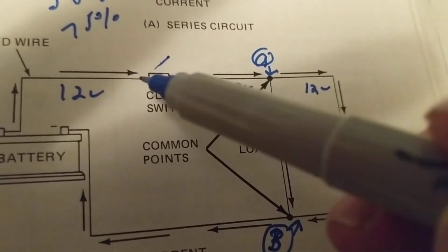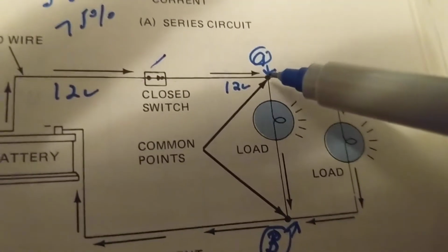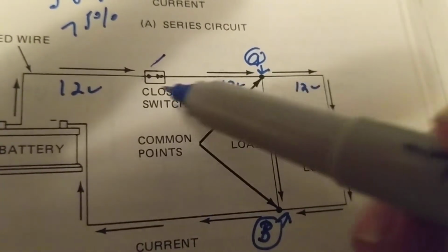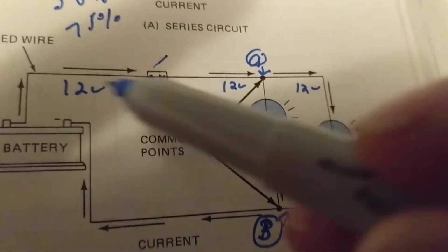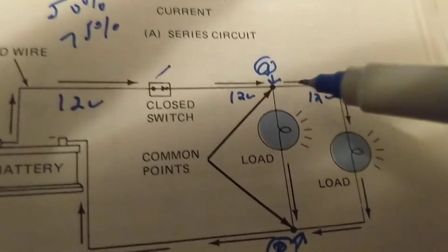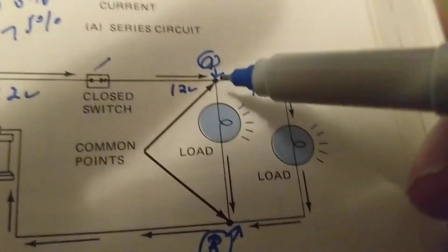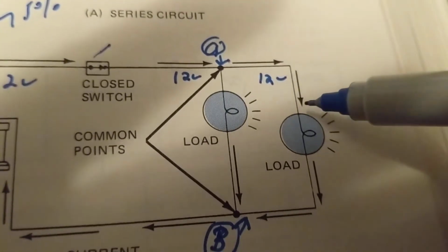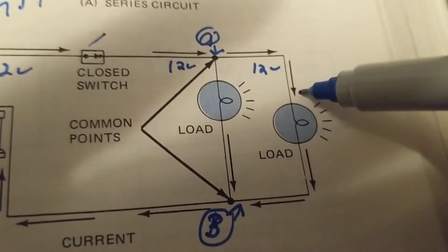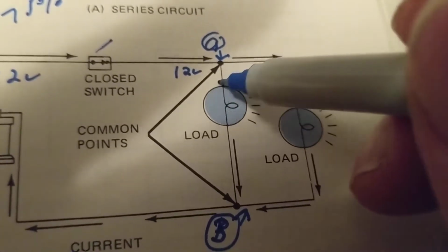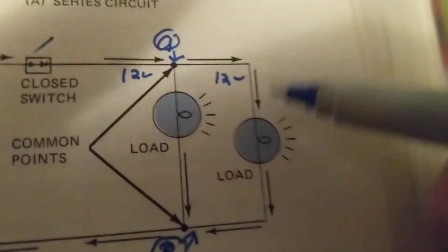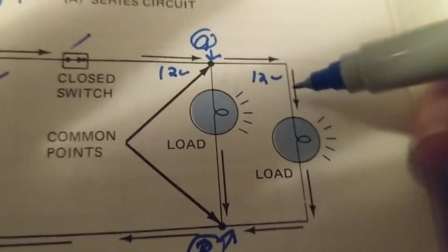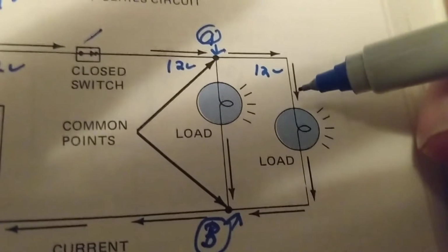Now this, we said was 12 volts here, 12 volts here. How much over here? 12 volts. Why? Because we did not lose any voltage drop through the wires or through the switch from the battery terminal. Now, 12 volts here, 12 volts here. How much should I measure at one side of this bulb? 12 volts. How much should I measure over here? 12 volts. This is a parallel. The same voltage here is the same voltage over here. Why? Because these are just wires. We did not lose any voltage through these wires.